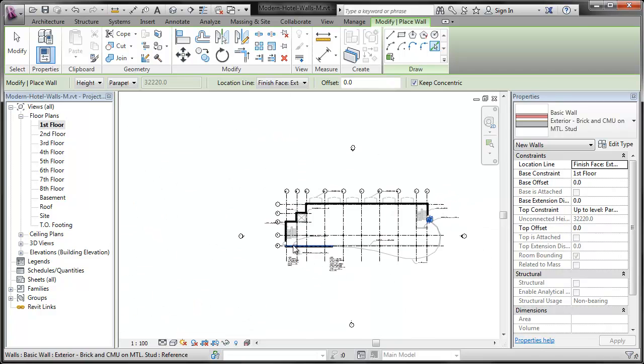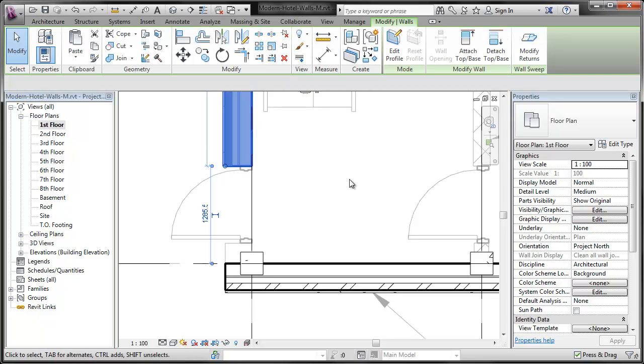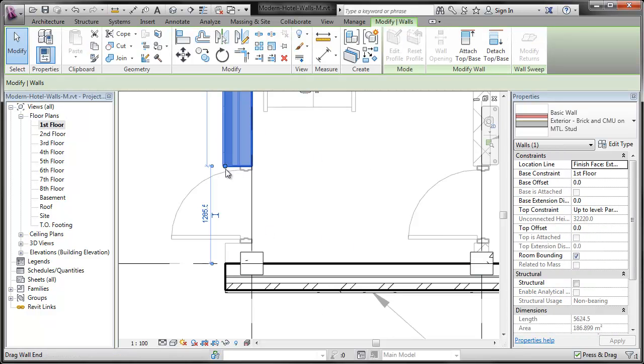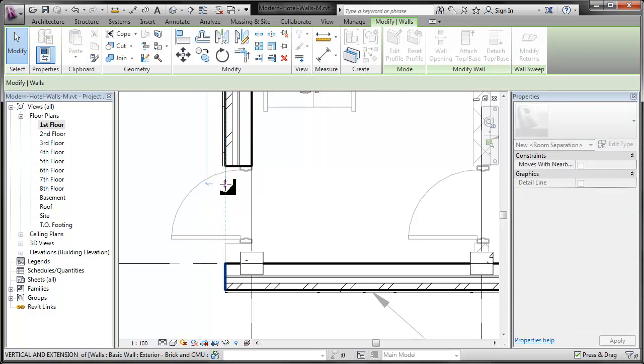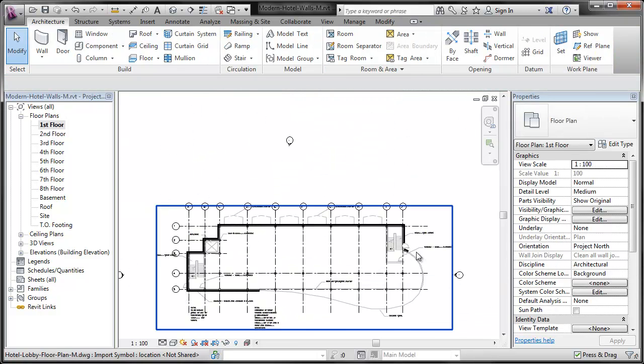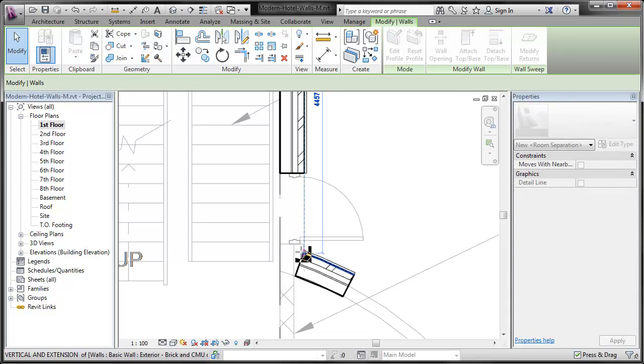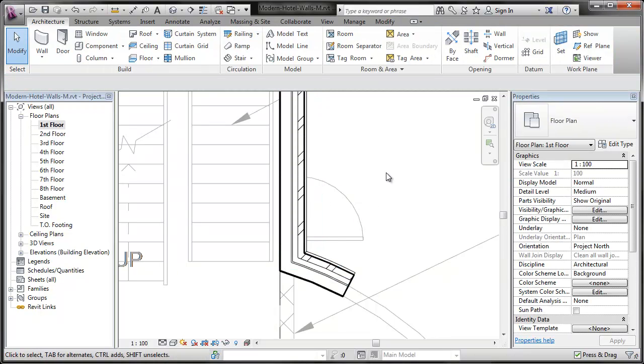And so forth. Now don't worry about the doors, because in Revit, we punch the door into the wall. But to aid that, we've got to select the wall, choose its little drag end, and then stretch it down, and Revit will heal it up. Likewise in this one, we can stretch it down and it heals it up.